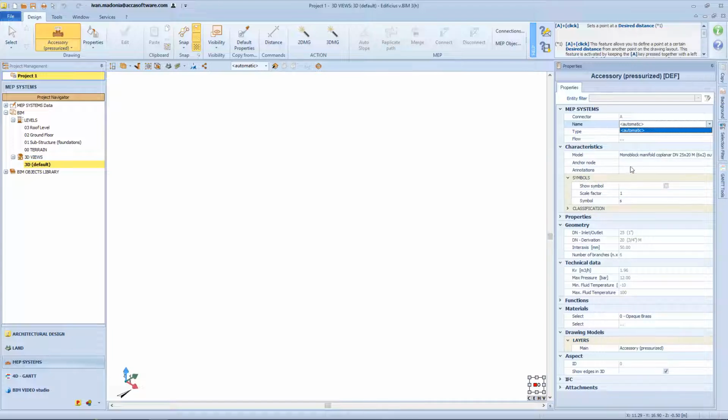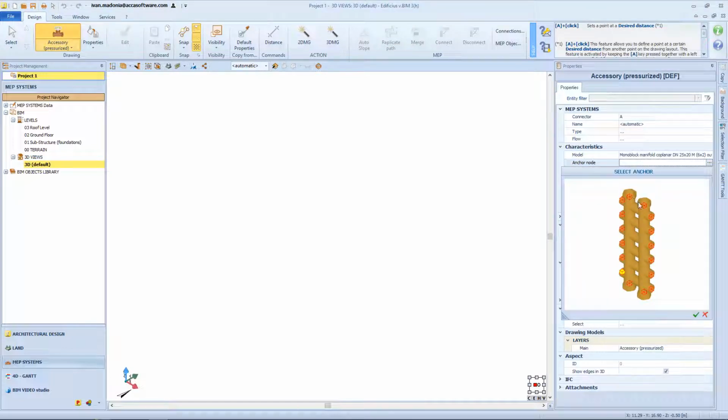The anchor field allows you to choose the position of the object grip, both before and after generating the object on the drawing. By clicking on this field and from here on the button with the 3 dots, a model preview appears in 3D space, to which red cubes are associated in correspondence with the connection ports. The anchor field is an alternative to the F5, F6 keys, as well as to the release of the object grip and its manual positioning, with the advantage of choosing the position of the object grip on the connection port.